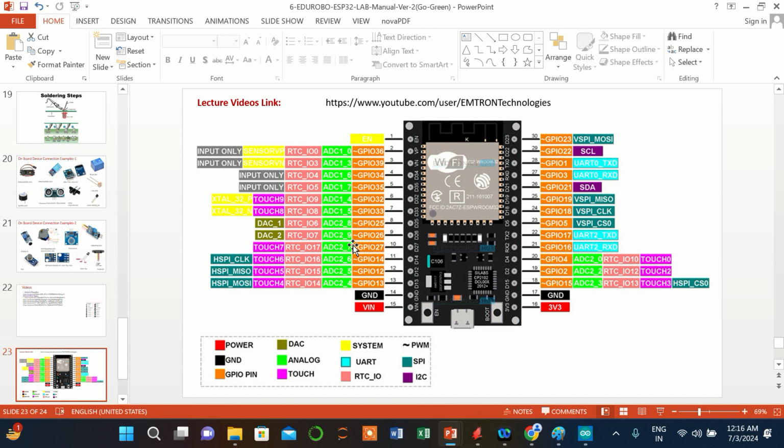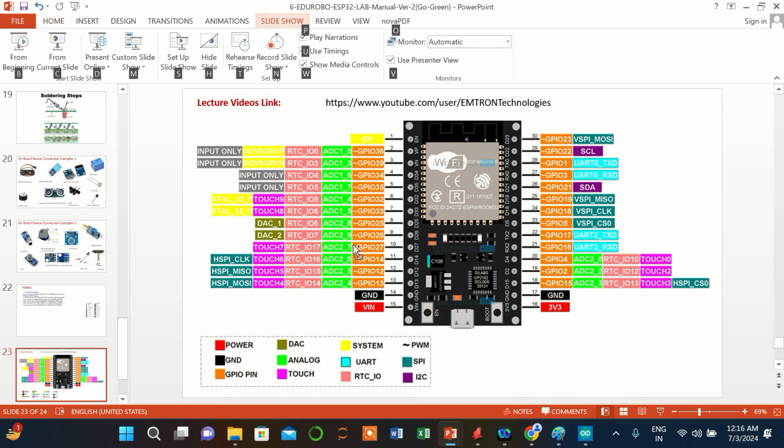It's altogether a different peripheral. GPIO is the simplest peripheral, as we have seen, like the LED. Similarly, input also is very easy to configure and understand. However, with ADC, you need to understand the sampling, amplitude, and other issues related to the percentage of error in quantization, linearity, and so on. So there are some other issues we need to understand. All right.